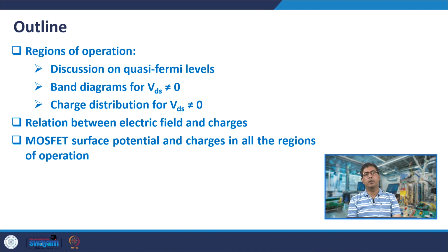So, quasi-equilibrium condition is also not valid, and we will discuss charge distribution. We will discuss in different regions of the device what the electric fields, electron and hole concentrations, etc. are. And we will then discuss the surface potential with respect to regions of operation of the device.